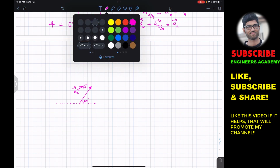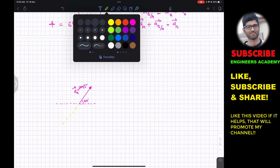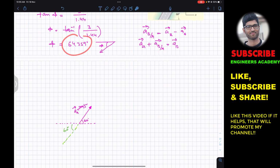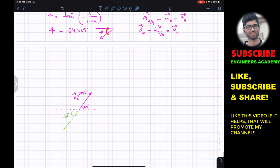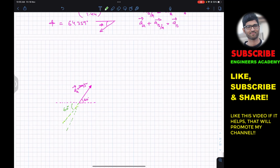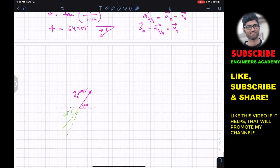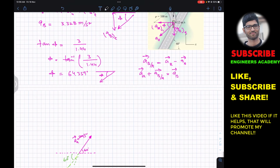Let me extend the line of action of AA like this. This angle is 60, but from this calculation we know that AB is making 64.359 degrees in this direction, so it will be somewhere here, approximately 64. So now this will be our AB, and the AB magnitude is 3.328.